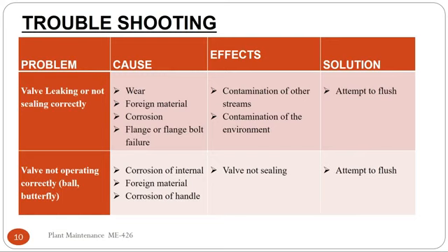That's why the latest standard says there must be at least two barriers on the suction side. It means that there must be two valves installed on the suction side of the tank. As we discussed in the last lecture, an NRV, a check valve, is installed. Other than the check valve, there must be two valves installed on the suction side of the tank,